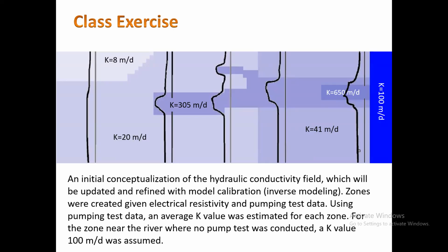Let me do one more simplification for the case studies that we will be doing. I'm telling you that H is not changing with time. H is constant. This is the steady state, where your H is not changing with time. So we can assume that this term is 0, and this will be our governing equation for steady state condition for groundwater simulation. We are simulating groundwater in steady state condition, where the system reaches an equilibrium stage, so that H is no longer changing with time.